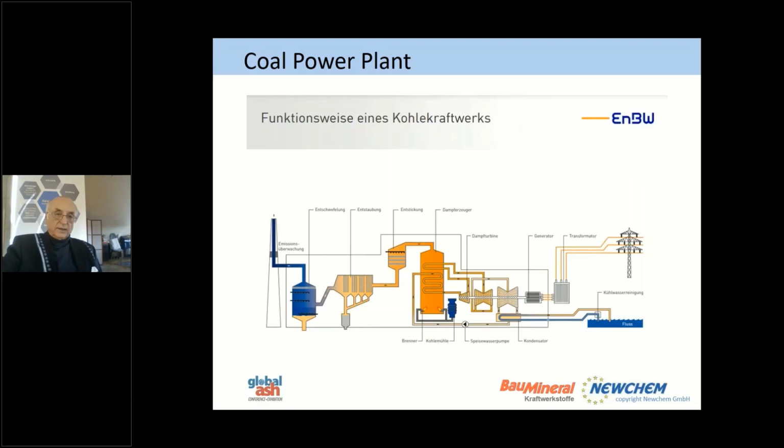the material. Here then the material goes into a spraying tower where we spray lime slurry on it to bind the sulphates, and out comes here gypsum, which is called the reagips, or reagent gypsum. And here the flue gases go out into a chimney, which we will show later.